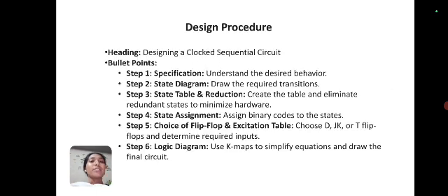Design procedure. Designing a clocked sequential circuit. Step 1: specification. Step 2: state diagram. Step 3: state table and reduction. Step 4: state assignment. Step 5: choose the flip-flop and excitation table. Step 6: logic gates.